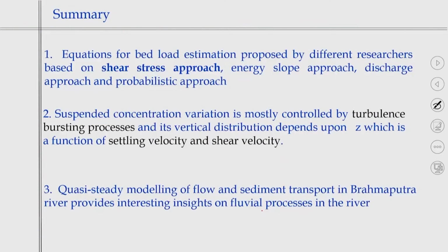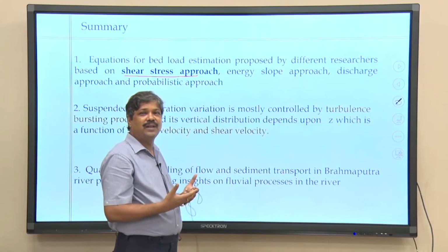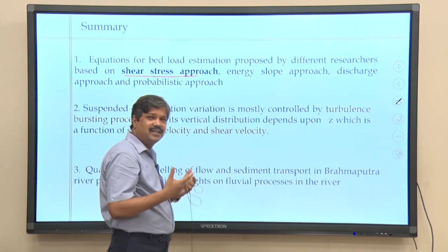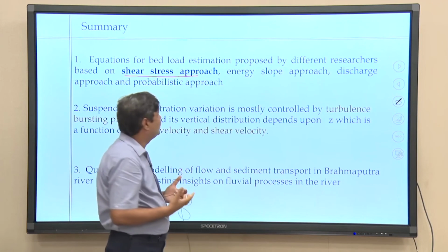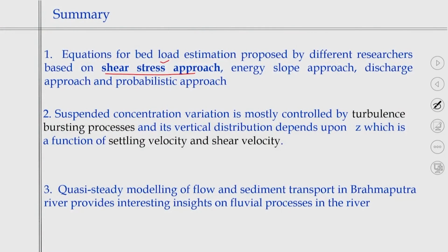We discussed that there are different types of bed load equations, and the shear stress approach gives better results for these studies, but I do not want to say that this equation is best. That is the reason why, as river engineers, we have to take a number of bed load equations, test them and find out which is appropriate. I cannot say the best equation, I can say the appropriate equation to estimate the bed load. More often I suggest having some sample data, theoretical data or literature data to validate the bed load you are estimating.